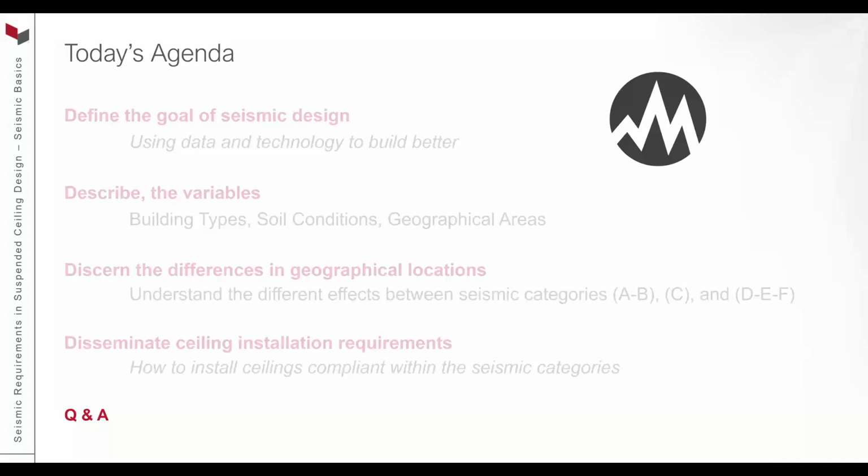Okay. I would have to read through that again. Basically, ASTM dictates that C636, C635, they only apply in specific categories, right? So if we're designing in category A and B, then we're going to use 635, 636. If we use category C, we're going to use 636 and ASTM E580. And then category D, ASTM E580.